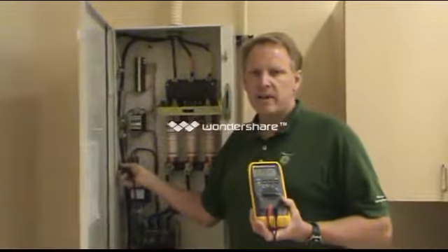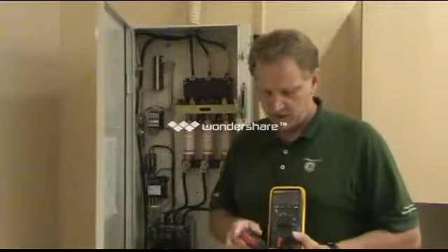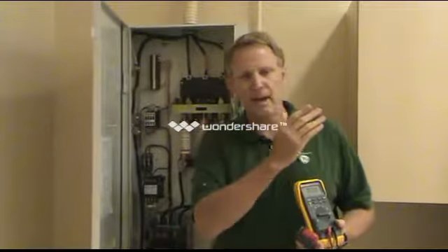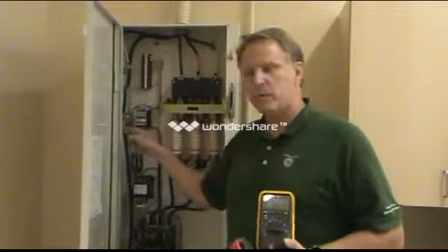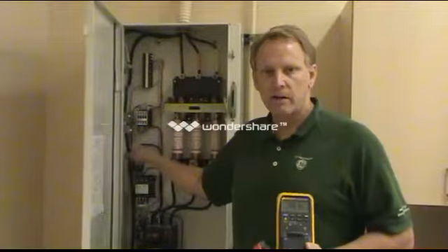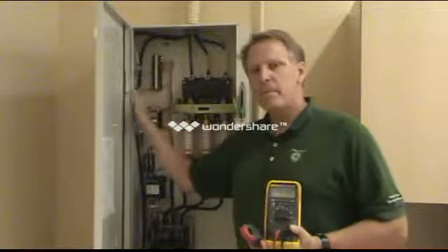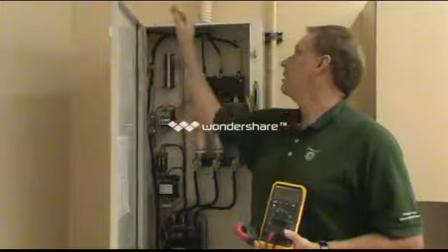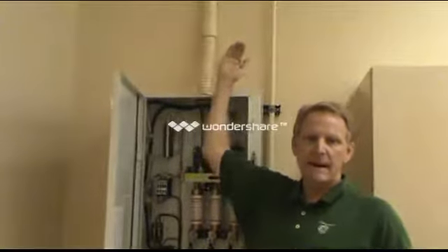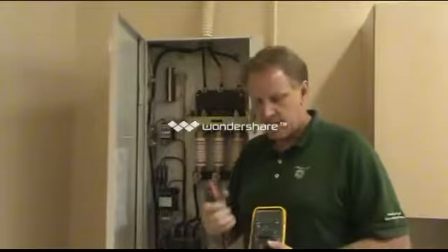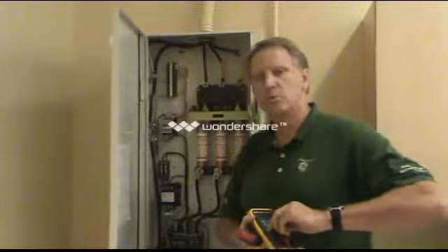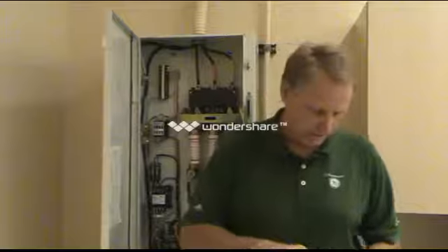All right, that's going to give us some valuable information here, because basically we have one ground path from our equipment to this point right here, and that's going to be through our 1-aught ground cable. Going back, you're going to have 2 paths. One is going to be your ground cable, but the other path is going to be the frame through the metal conduit back to the source. So there's 2 paths going backwards. That's why we have to take multiple readings. There's ground currents.